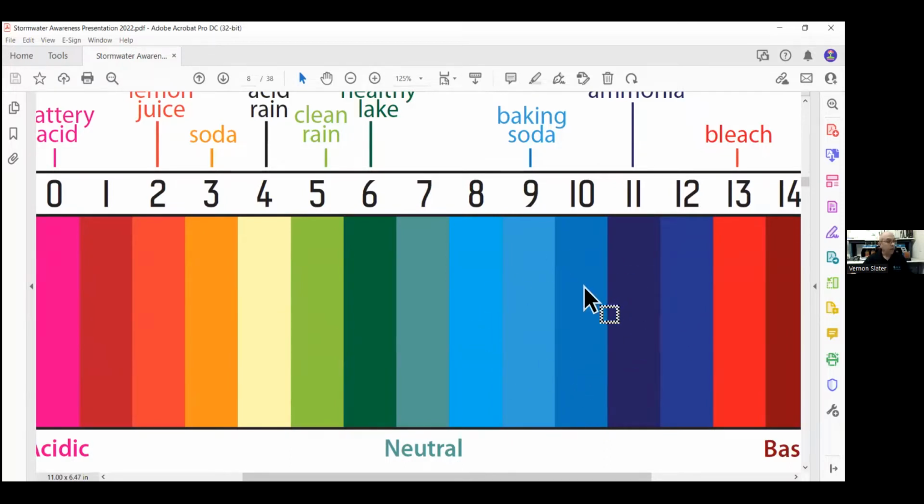Different treatment technologies may require different pH ranges for effective contaminant removal. For example, a popular coagulant used in treating construction stormwater runoff is a product known as chitosan acetate. Effective pH range for this polymer is lower than pH 9 and above pH 5. At a pH of 10, the polymer just will not work. And then to raise a low condition, we could use sodium bicarbonate or more industrial chemicals like sodium hydroxide. But when you start using these industrial chemicals, you got to start thinking about cost, handling, and how they're going to be injected so you don't end up injuring somebody or yourselves.